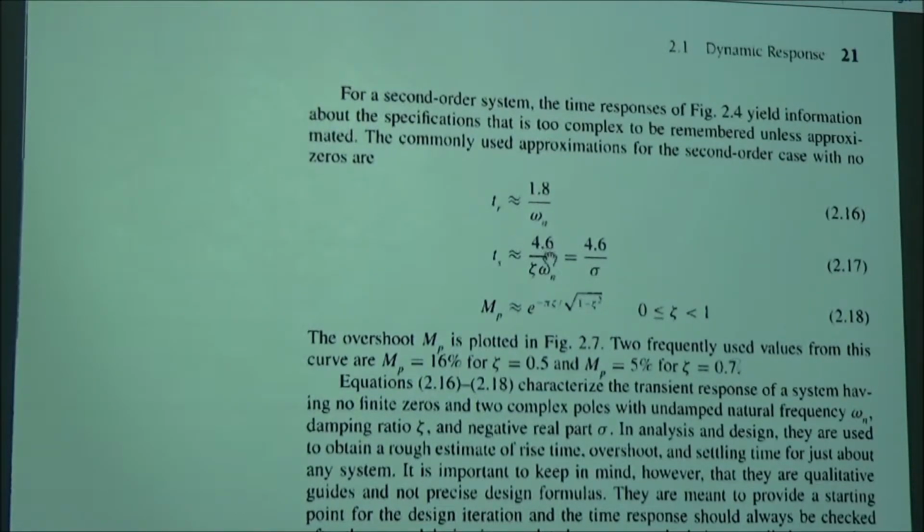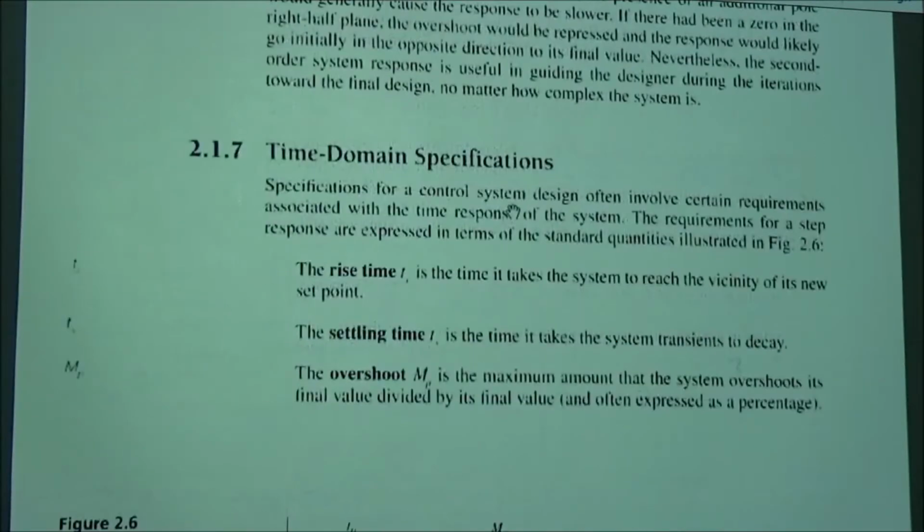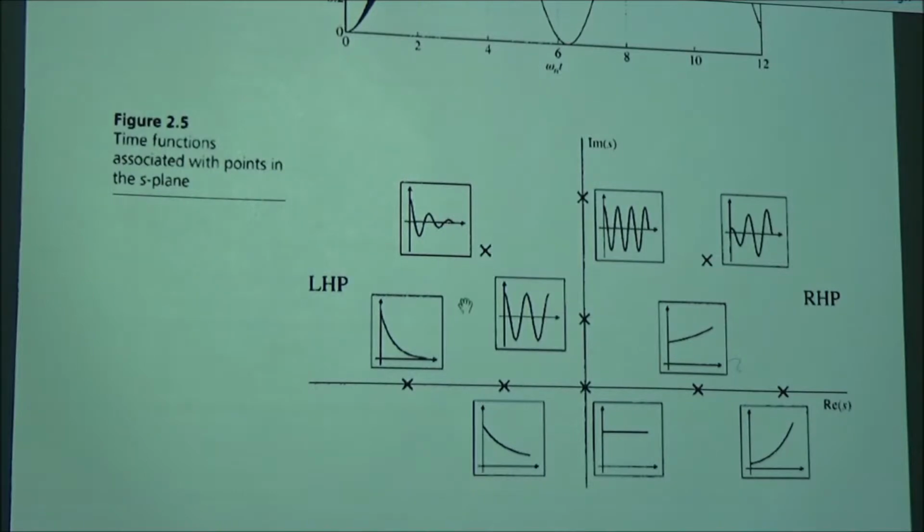You have to note that these conditions are constrained by the following factors. They have to represent a linear time invariant system. It is approximately for a second order system which has only two poles in the left half plane, one here and one here, let's say. Because conjugate poles, as you know, they come in pairs. They don't come by themselves. So if two of your many poles are close to the j omega axis compared to way back here in some other poles, these two poles are called dominant poles.